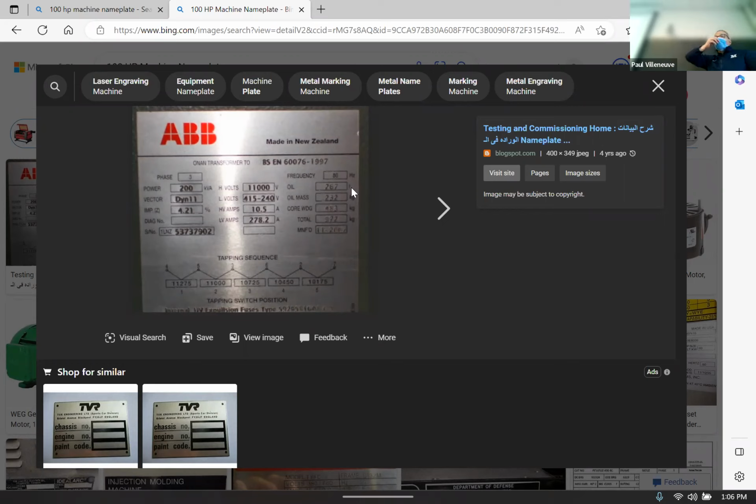But that's one of those things you never want to try to push. Most motors, if you buy it for 10 horsepower with service factor 1.15, are more likely running at, like I said, 9.3, 9.2 horsepower, because they will run overloaded, meaning over their normally rated power.